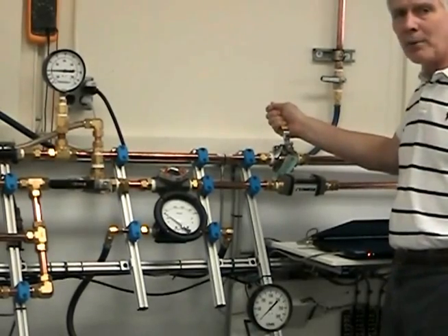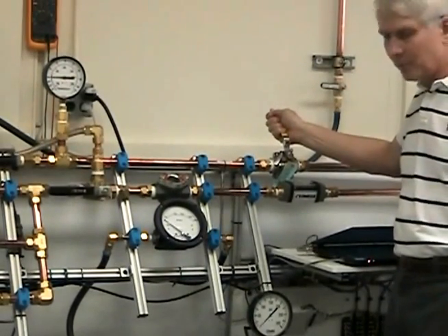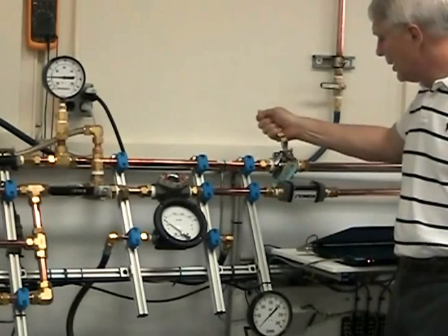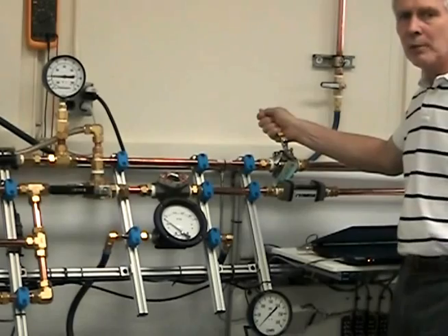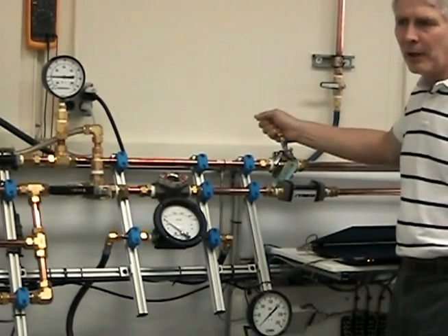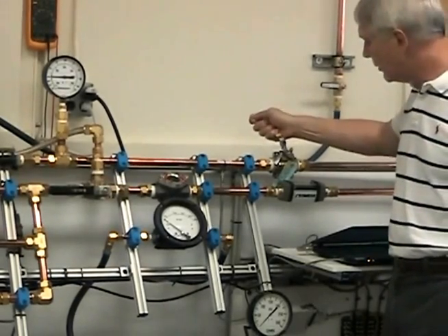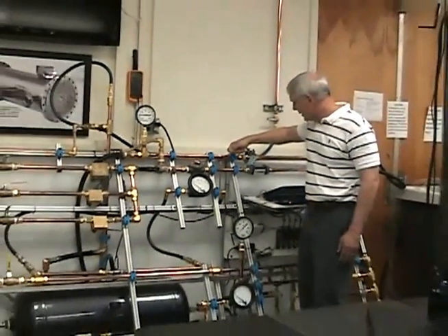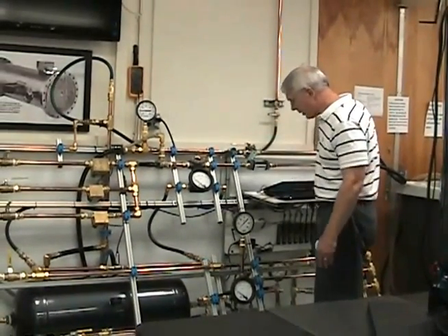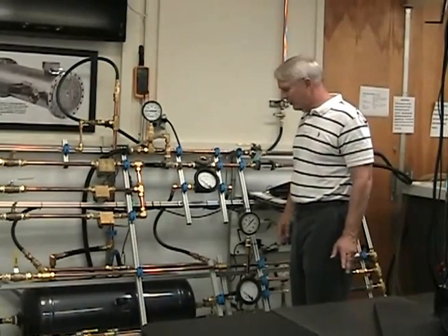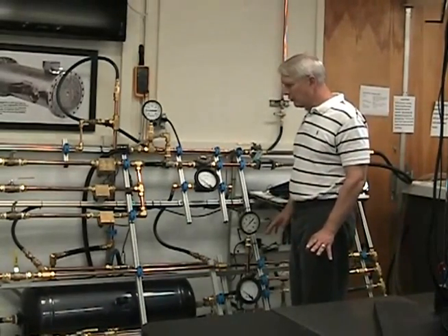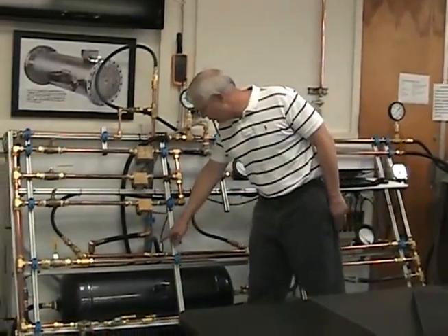Normally we don't want to operate it with the valve completely closed because that's going to put a big load on the pump and create a problem. And there's really no reason why we need a zero flow rate, because at a zero flow rate our friction factors and so forth have no meaning. Okay, so we'll open that up. In order to measure the pressure losses, we have several instruments. What you're going to use for your data is a transducer.